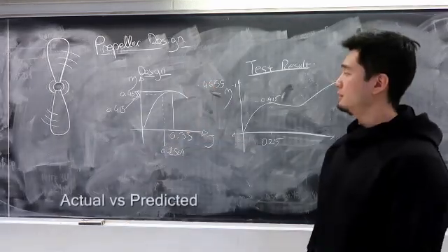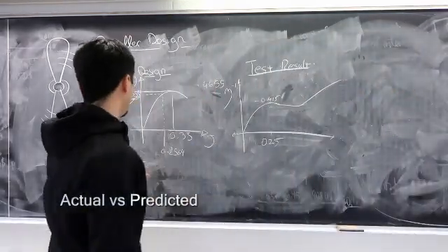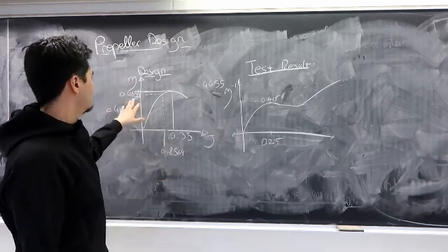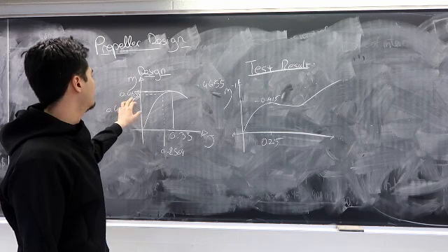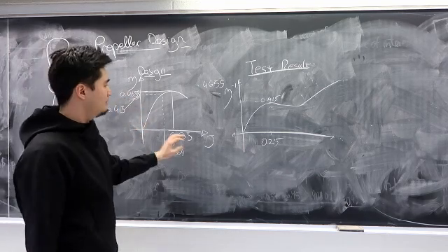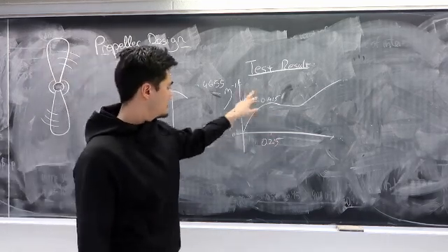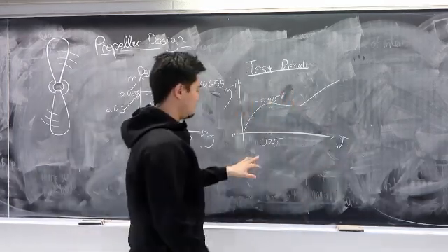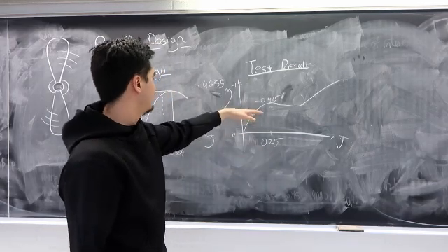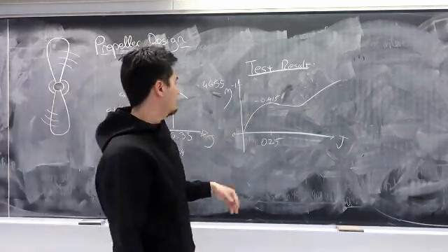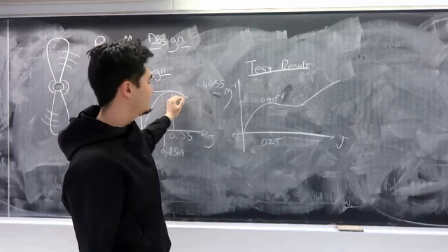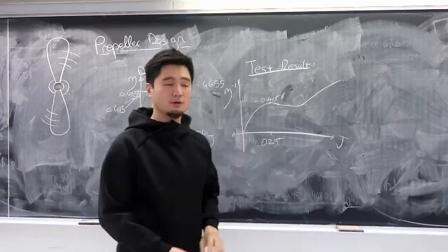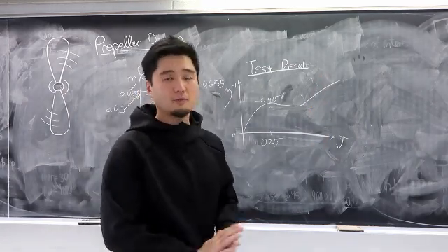Just to go over the test results a little bit, what we designed, target was around 0.25 advance ratio. We were expecting close to the maximum efficiency of 0.4655. In reality, the region of J where we expected the maximum efficiency to occur, around 0.25, was 0.41, so that's close to what we expected. But the unexpected part was that we expected the efficiency to drop, but the test result came back with something that just went higher. So I think maybe the probable cause for that was that